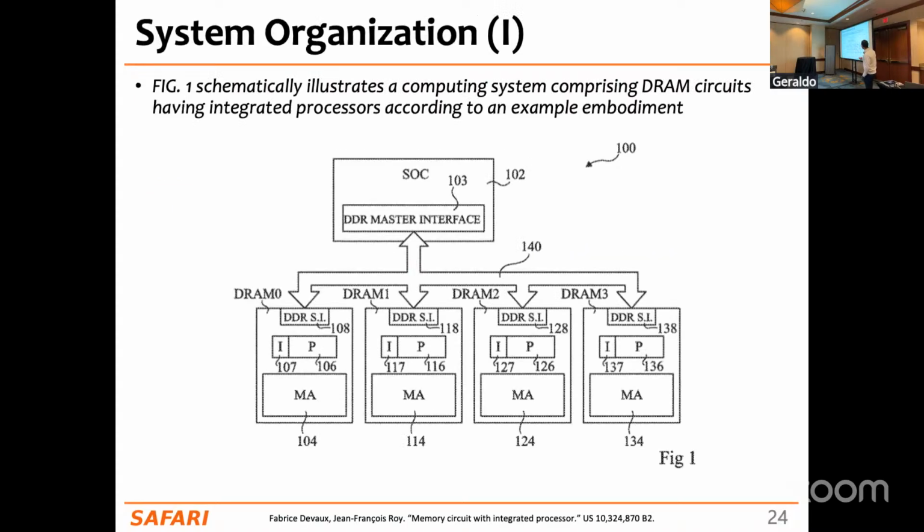Internally, this is a picture from the patent that the UPMEM company first filed. What we have here is your main SoC, your host CPU. Then you have a master interface that connects several DRAM DIMMs. And inside the DRAM DIMM, you have some DRAM banks, an in-order processor, and some SRAM memory for instruction cache and scratchpad memory as well.